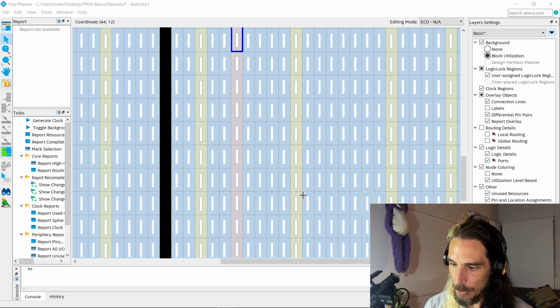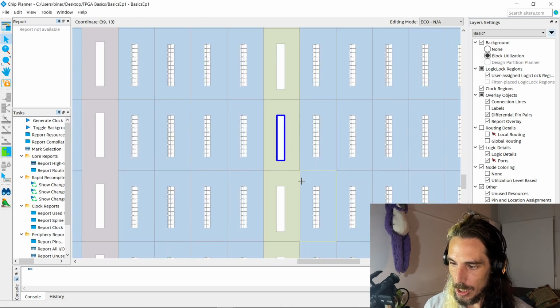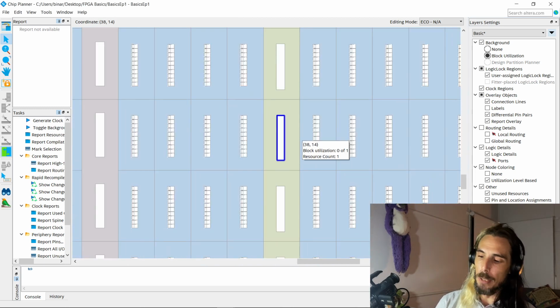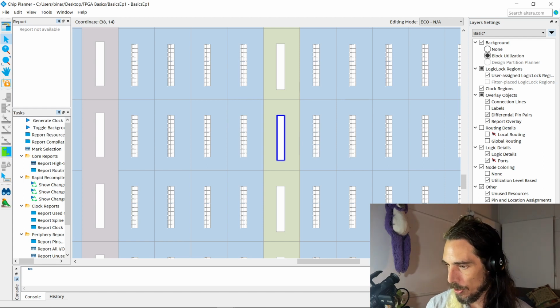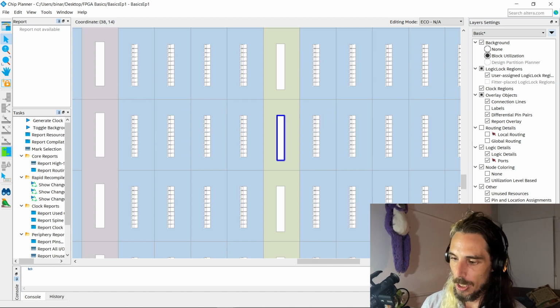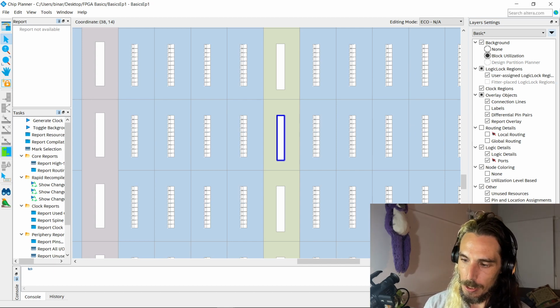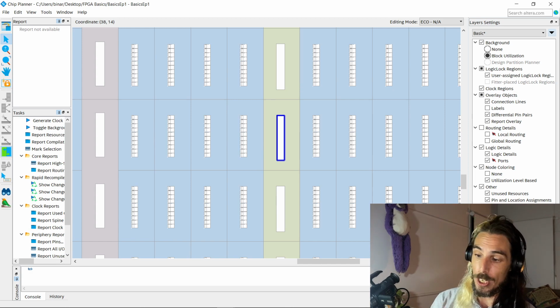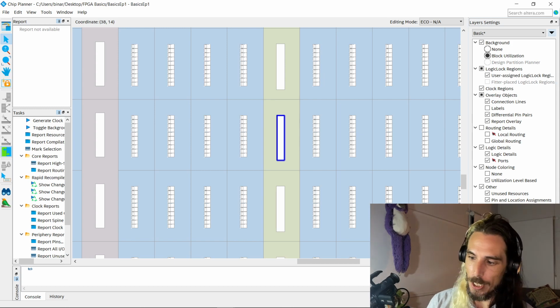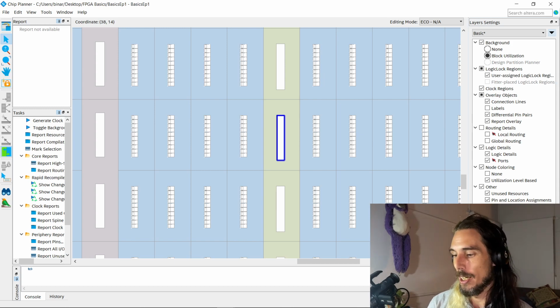We've also got the green ones, which are basically RAM. And those RAM blocks, each of those guys, I believe it holds 10 kilobits. Those guys can be used as just normal RAM. They can be used as ROM, so you can preload values into them, and they can be read by other parts of the circuit.